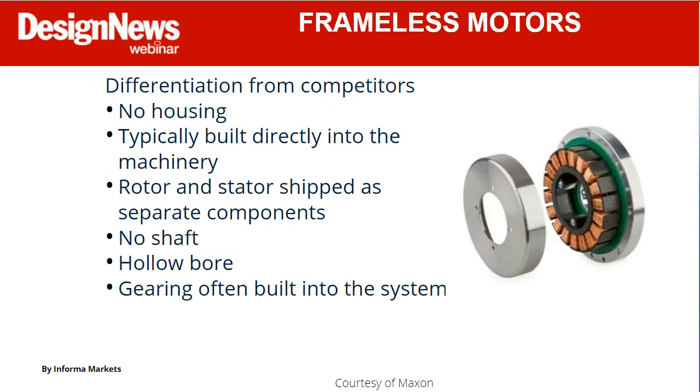Now, to me, the ultimate kind of customization thing comes through your frameless motors. And that's a way that really, especially for things like robotics, is a super interesting way to differentiate. So, anybody can get a housed motor, but if you get a frameless motor, you're getting your rotor and your stator shipped as separate components so that you can build them directly into the machine.